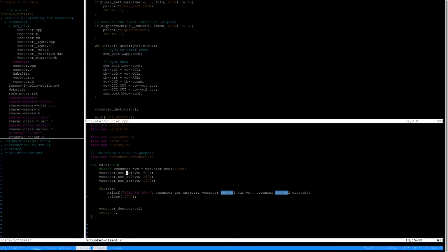So this is how you can use shared memory and timers on Linux, and this is how you can also simulate Verilog hardware on Linux and kind of make it easy to use and make it possible to create simulated hardware that you can then write code that uses the simulated hardware as though it was microcontroller hardware. So, any questions?